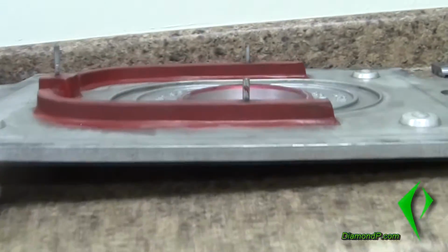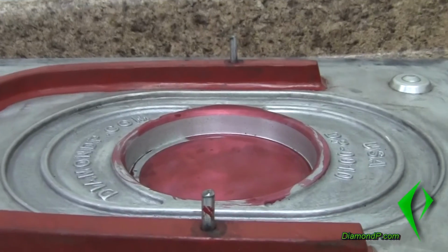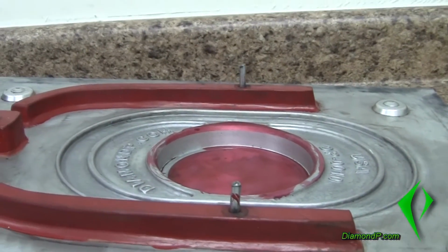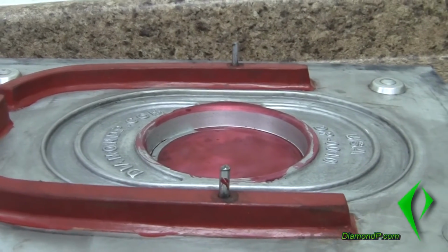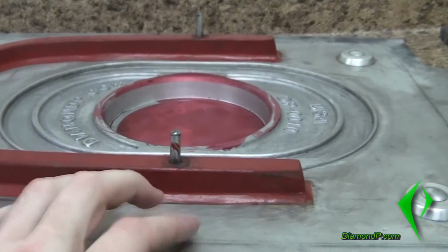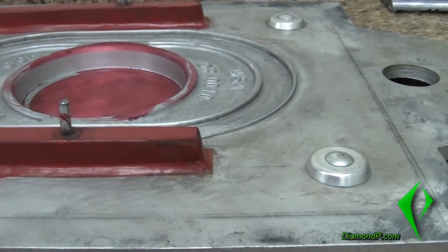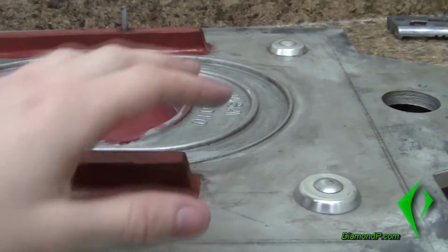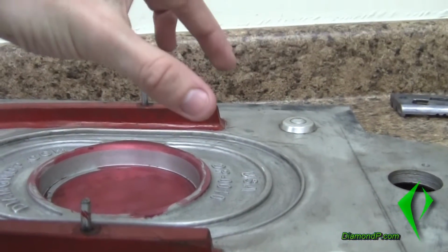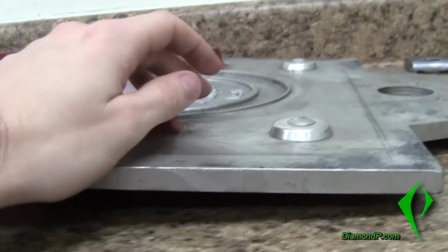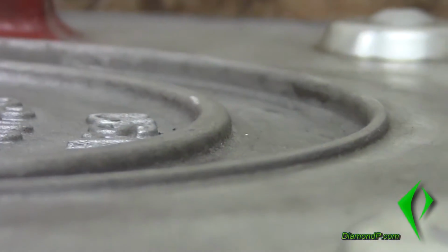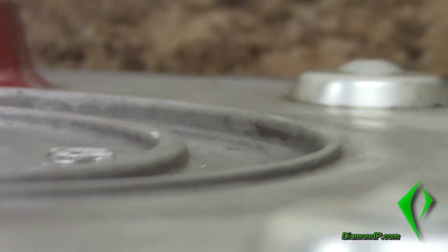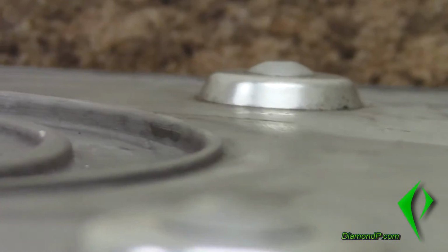I know that probably doesn't make sense. It's something you have to see, and you can watch some of my later videos to get a better understanding of that. But the draft of your part is directly controlled by your parting line. Wherever you have your parting line, anything that's sticking out of your mold has to be drafted. It's kind of hard to see, but if you look closely, these walls have angles on them.